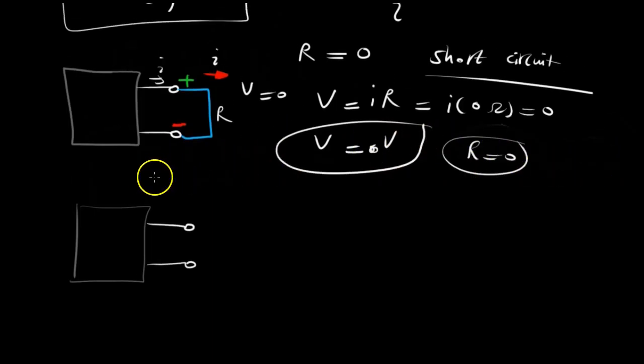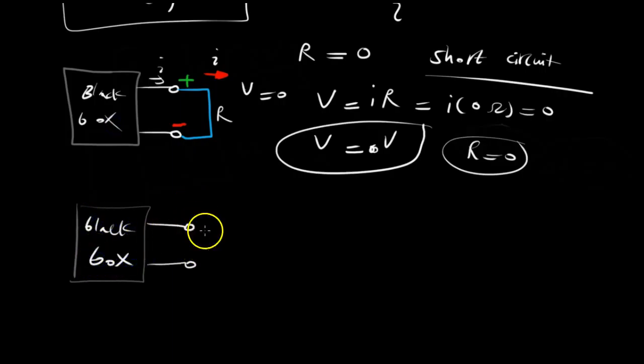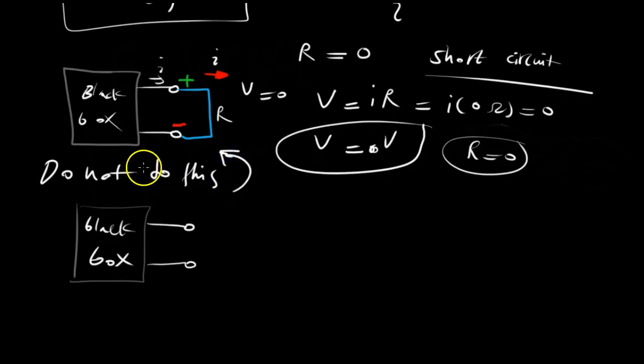The other situation is when you have another black box. Let's call these black boxes. Something's going on inside that we don't know what it is, but once we connect a wire across the terminals, which again, you should not do in the real world. You should not simply connect wires in a laboratory across some load, because you do not know the voltage-current relationship inside, and you may have a very high current rushing out, burning something up or damaging components.